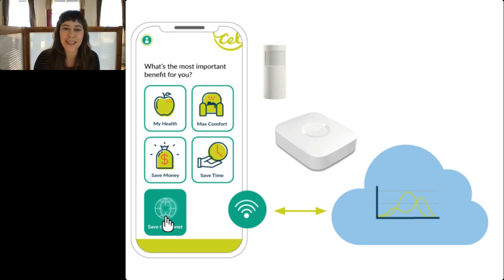But once you start messing with heating and cooling, now the fish are in the fishbowl and you're going to have many more overrides. So as we start to look at how the whole portfolio of devices works in a building, to enable us to do things like preheat and pre-cool without treating each of these devices separately, when we look at the building as a whole, it's worth more than the sum of the parts. However, because some of the devices that we're playing with really impact user comfort in addition to decarbonization and ampacity of the building, user preferences have to be factored into that intelligence.